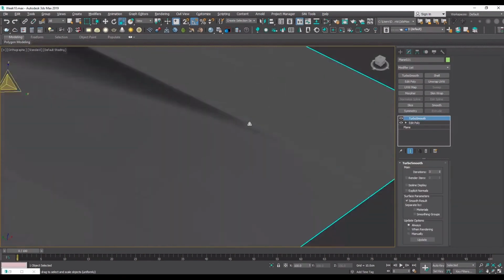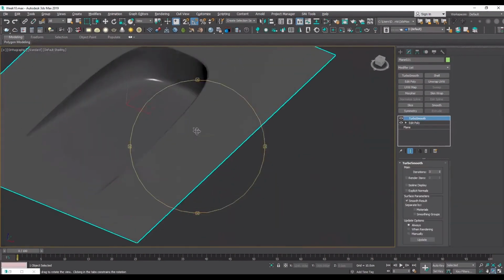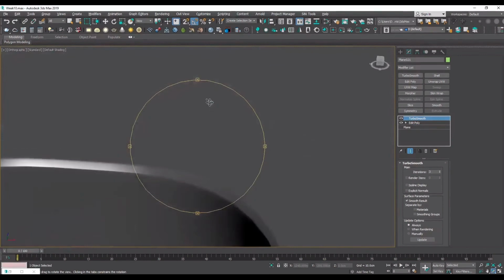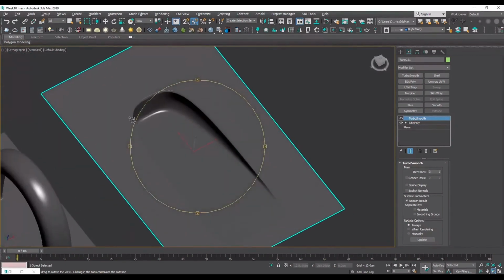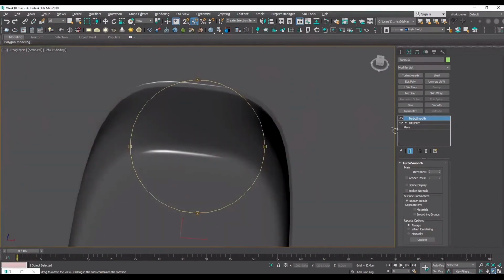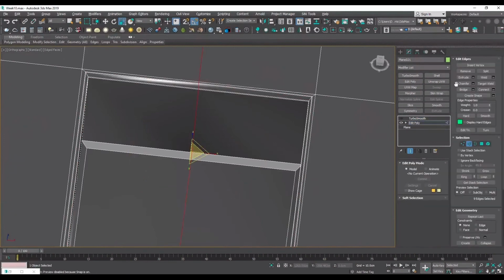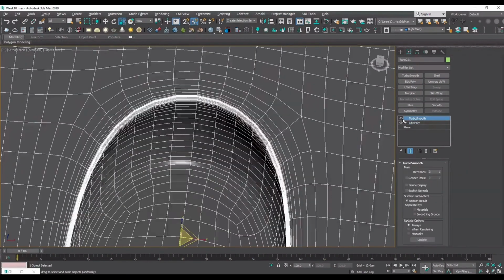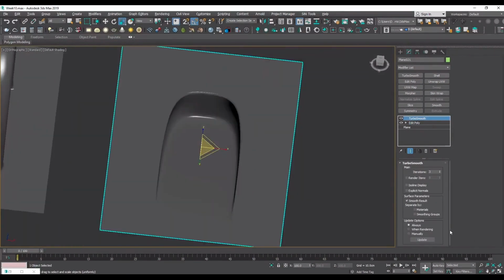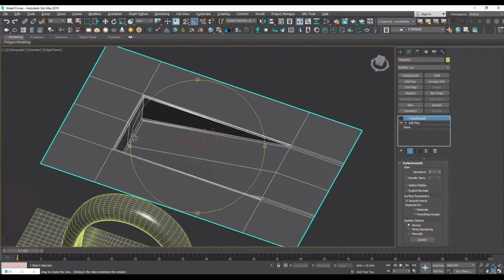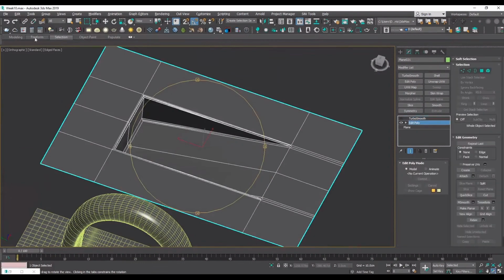Snap that to this vertex, and you see the chamfer effect here. It's so sharp around the corners. We can see the shading effect. And by the way, you can absolutely be free in what you do. You can keep the curvature and delete the middle edge, or you can keep the middle edge and limit the curvature around there.